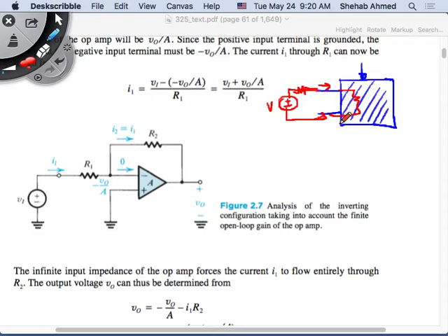You short all the supplies. This circuit happens to have no supply, assuming there's no supply in the circuit, of course, because if there's a supply, it will ruin this measurement. You cannot measure a resistor value using an ohm meter while it's in the circuit. You can measure the voltage across it using a voltmeter, not an ohm meter. There's a difference there, right?